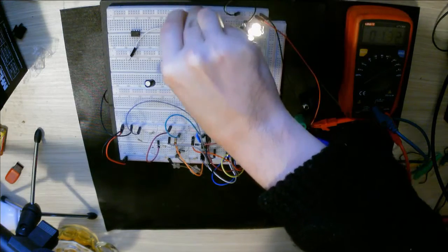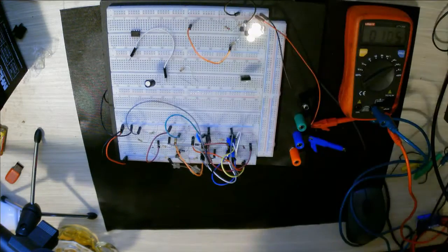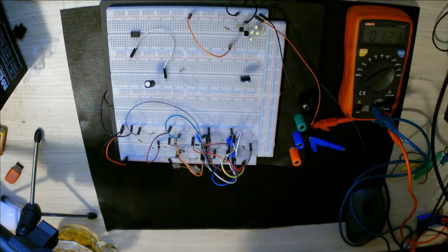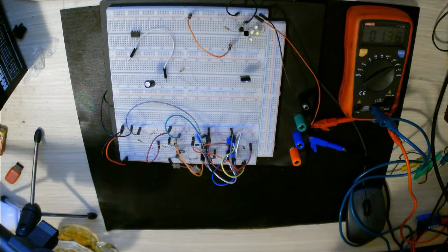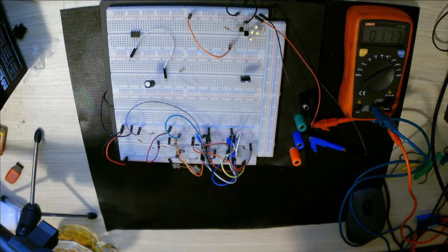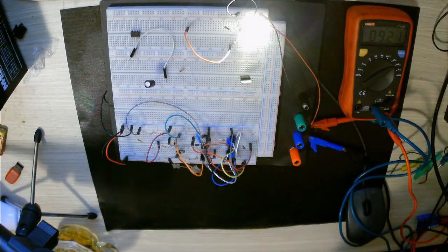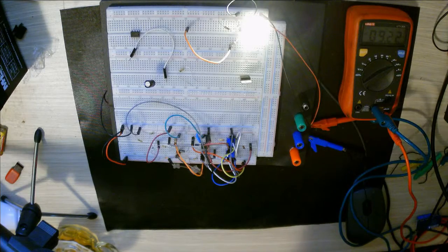when the power comes back, well, it won't matter because the power will be back. When the power comes back, the circuit will switch off the LEDs and draw a bit more current. I'm just going to increase my voltage to the 13.8 maximum. So this circuit represents, when in off state, a maximum of 2 milliamp draw, and when in on state, a maximum of 9 milliamp draw on the system.